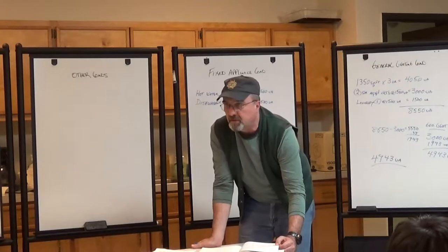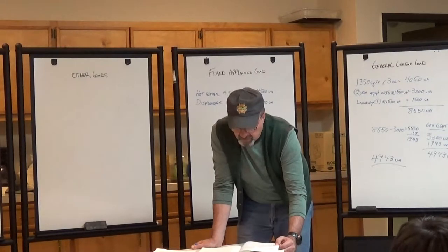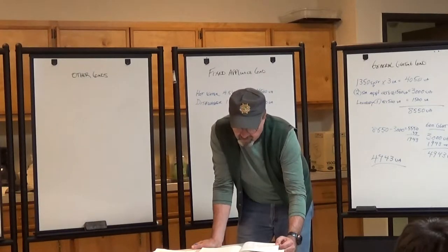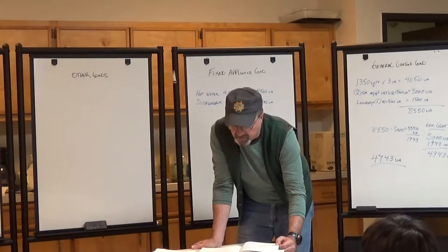We're going to be looking at single-phase 120-volt motor. And in this case, the disposal is a 1/2 horsepower. So we go down the 1/2 horsepower column, 9.8, and we look at what's the closest. We got 115 volts, 9.8. It says 9.8, right?